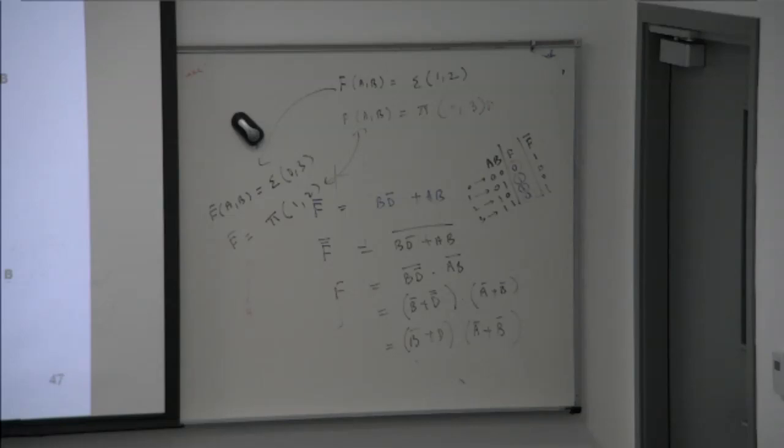Now what can we combine? It cannot be combined with any other one, but this can be combined with this don't care. Now we have a bigger group. When we have a bigger group, this is B bar CD. What about this one? BC bar D, BCD bar.